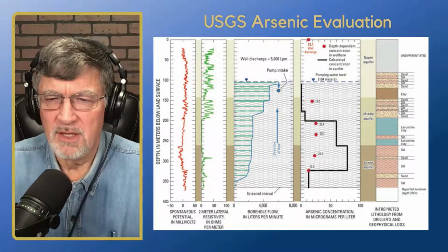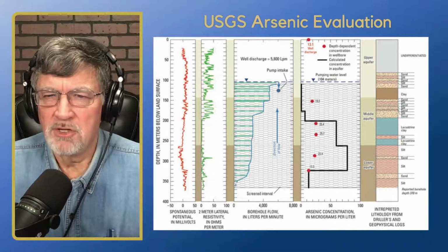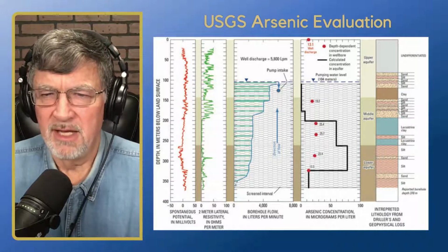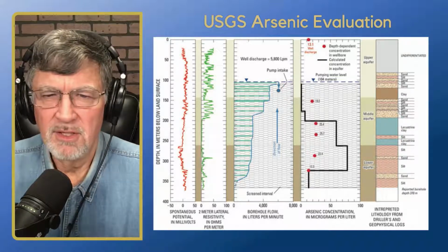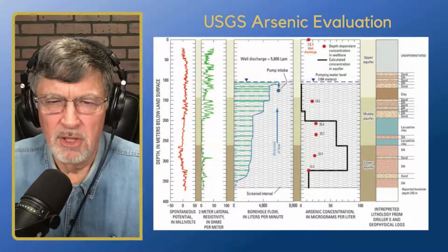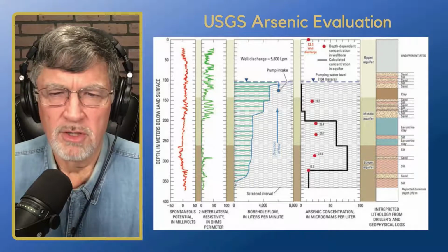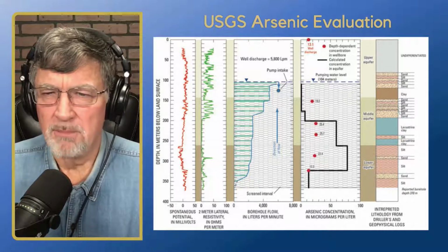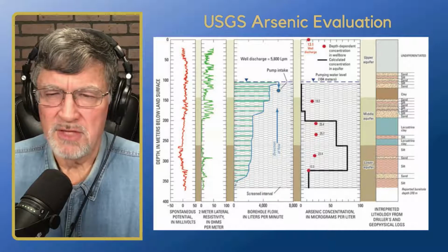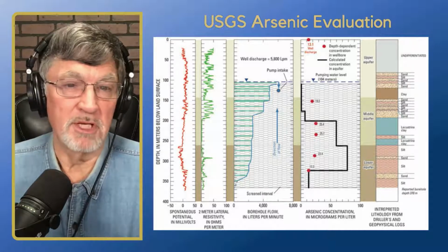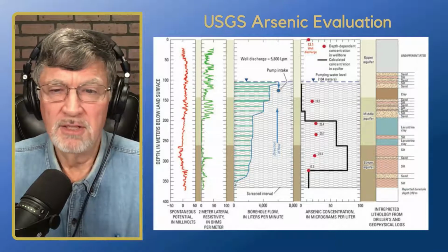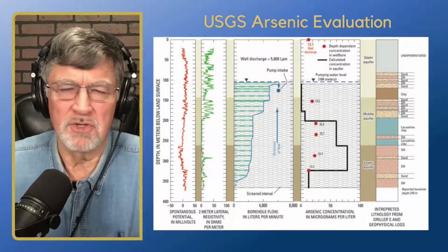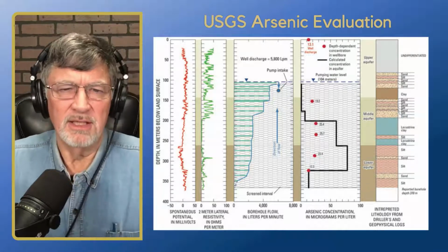And then off to the far right here, we have our geologic log, and we're kind of playing that out there too. And you can see down below, some of these lower resistivity bumps are actually in thinner sand zones, so that's pretty much to be expected. So there's some yield from those zones that we can see in our flow profile. So you can see how we really kind of put this whole thing together.